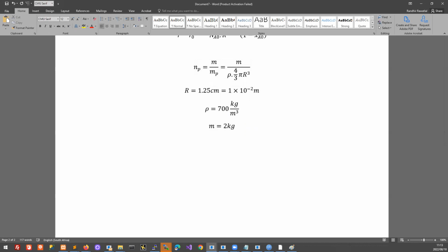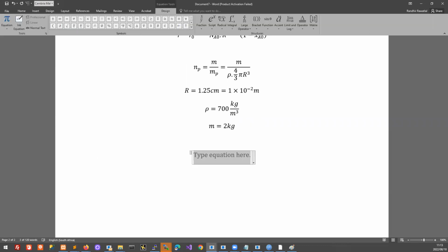Then we can say the total consumption rate of component A. So let's write it as dNA/dt. So that's the total consumption rate of A in the whole container. That consumption rate must equal the molar flux of A. So we know A diffuses towards the particle where it gets consumed. So we can simply take NA naught, the surface flux, that's going to be equal to the consumption rate, times the surface area.